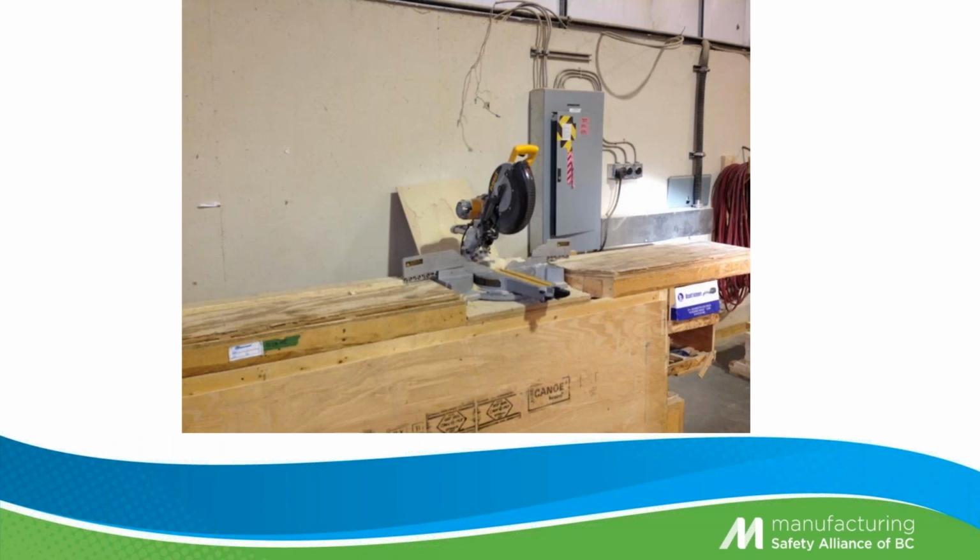So here we have the next one. We have a table saw and a compound miter saw, and one we're cutting, and you can see the dust on the piece of wood. They've obviously cleaned this up prior to the picture, but the electrical panel's open. All we need is a little spark with the fine dust to have a little flash, and then we can have the potential of a fire.